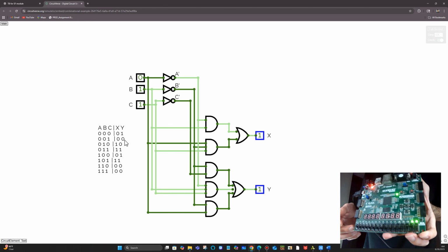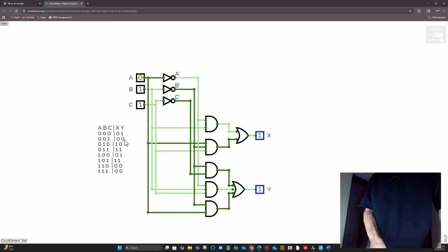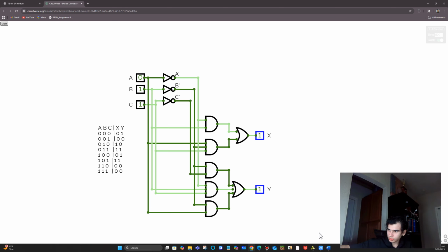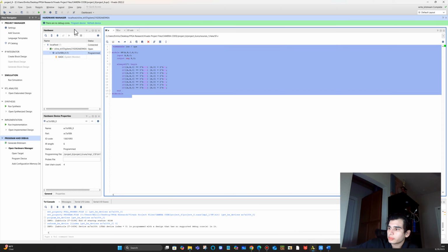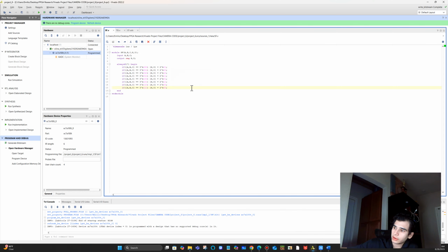So, yeah. We have created from start to finish a combinational circuit of our choosing as modeled by the table, created a Verilog file for it, and implemented it on an FPGA. If we had thousands of dollars, we could make a chip to implement that exact behavior and have it be mass produced. And while it might be pointless to do that for this simple circuit, you can do this process that we did for any digital circuit.